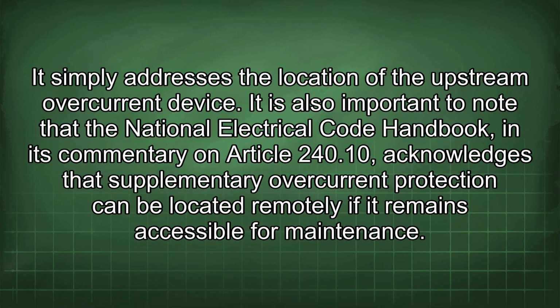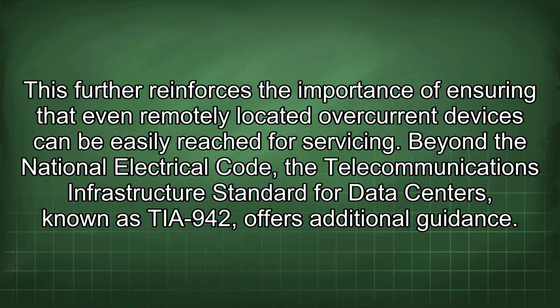It is also important to note that the National Electrical Code Handbook, in its commentary on Article 240.10, acknowledges that supplementary overcurrent protection can be located remotely if it remains accessible for maintenance. This further reinforces the importance of ensuring that even remotely located overcurrent devices can be easily reached for servicing.